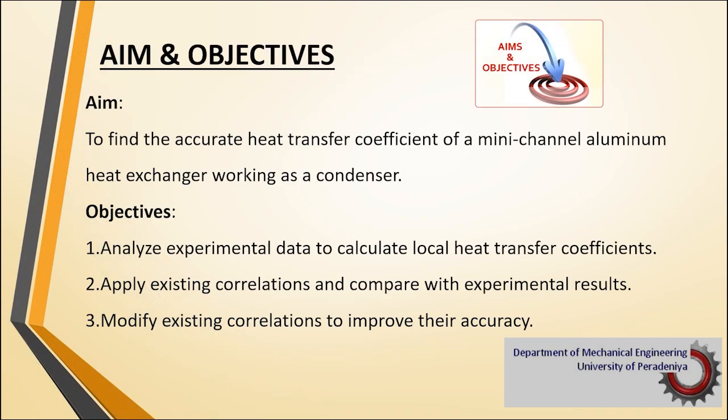The aim of my research is to determine the accurate heat transfer coefficient of a mini-channel aluminum heat exchanger operating as a condenser. To achieve this, I have set the following objectives. Analyze experimental data to calculate local heat transfer coefficients, apply existing correlations and compare them with experimental results, modify these correlations to improve their accuracy.